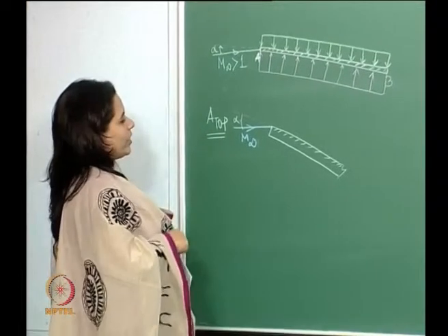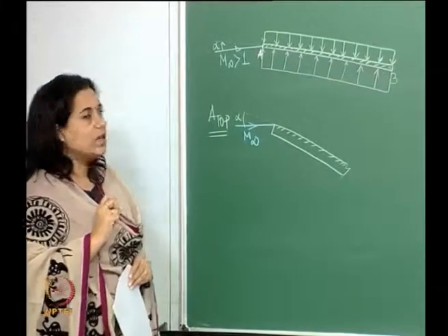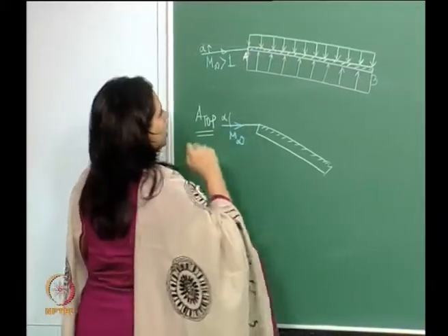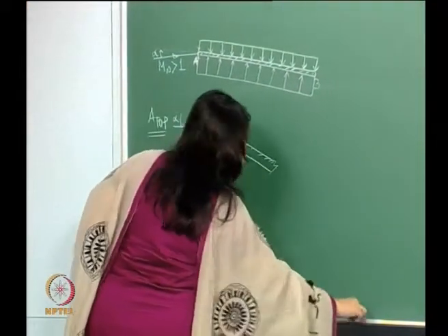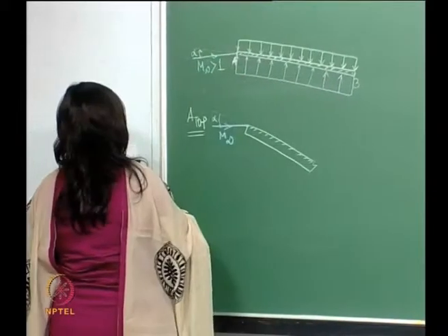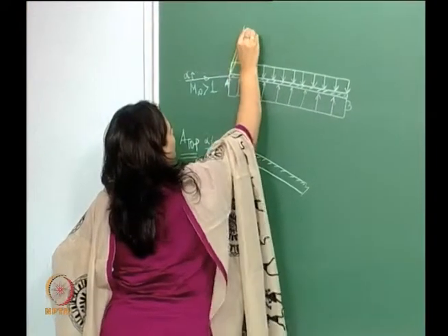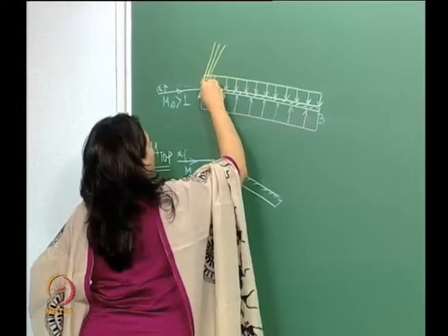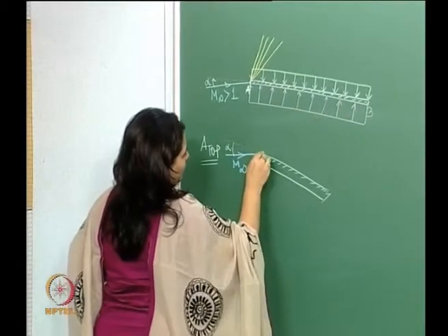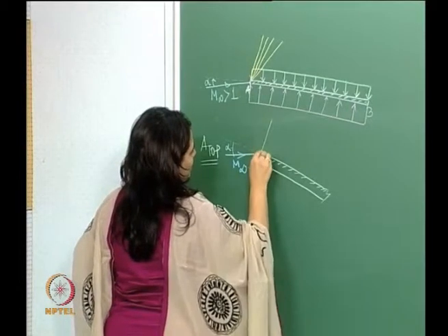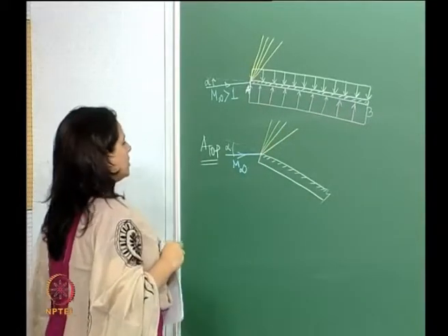From what we have learned so far, this is expanding over this corner. This is like an expansion corner here. So what we would expect to see over here is an expansion fan. Let me draw that right here. Let me draw it this way. What we expect to see over here is an expansion fan. And if I were to draw the same thing over here, this is the expansion fan.